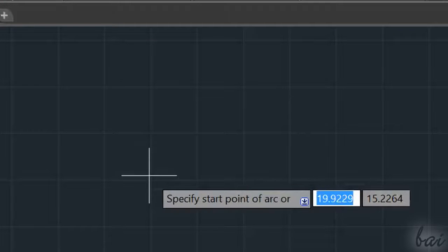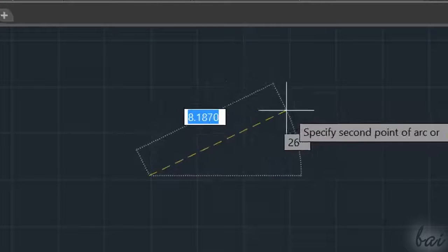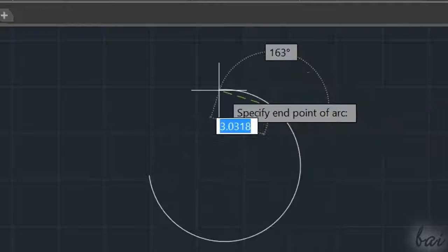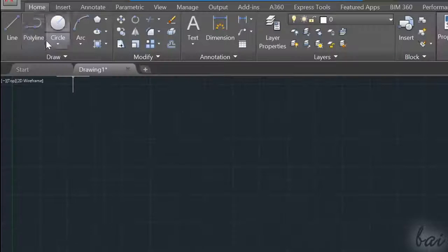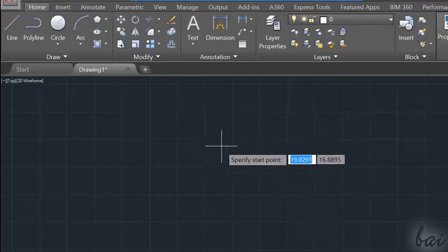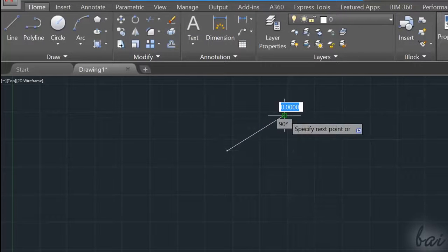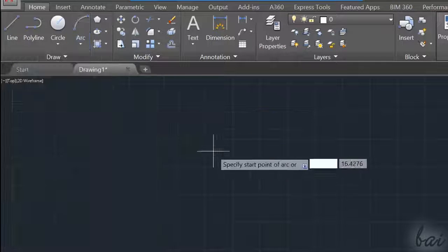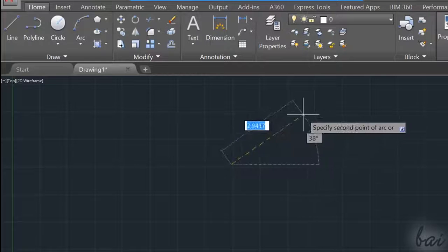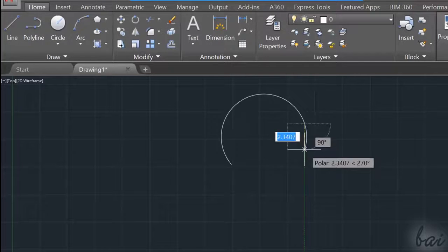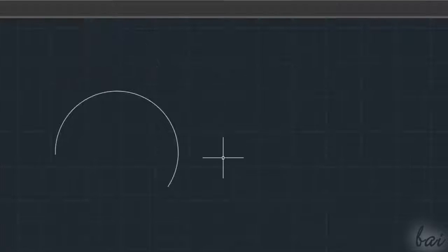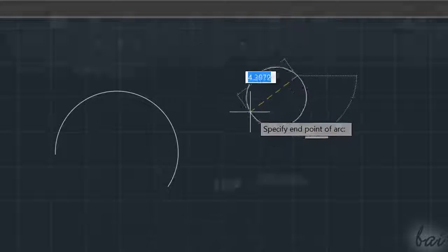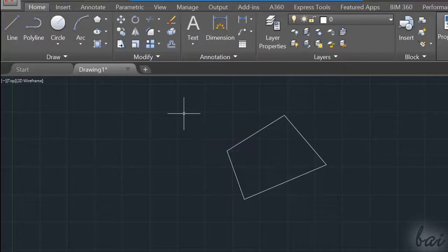While you draw inside your project, AutoCAD always shows a preview of the object, showing length and angle measurements. The object will be actually drawn when you fix the last point required. Depending on the tool chosen and on the object shape, you may need to fix points, distances, or angles. For example, if you choose to draw a 3-point arc, you have to fix a first point as center, fix the radius with the second point, and then the third arc angle with the third point. Plus, if you press the Enter key, it will enable you to use the last tool that you used. Use Escape key to undo your current drawing instead.